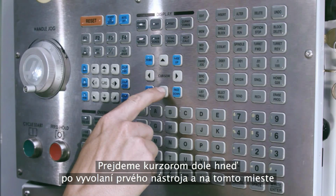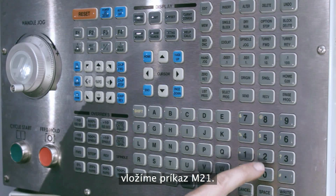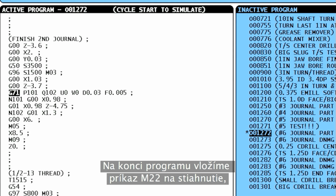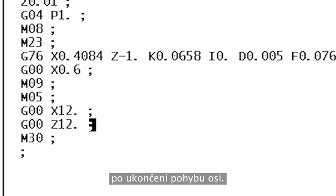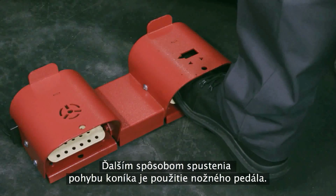We cursor down to right after the first tool is called, and this is where we insert the M21 command. And at the program's end, this is where we'll insert the M22 retract command after axis motion is complete. Still another way to initiate a tailstock move is to use the foot pedal.